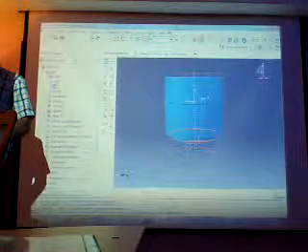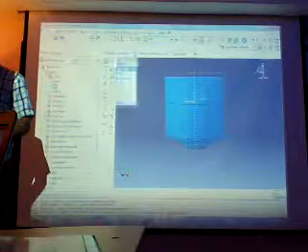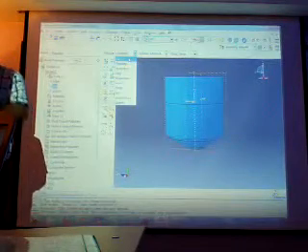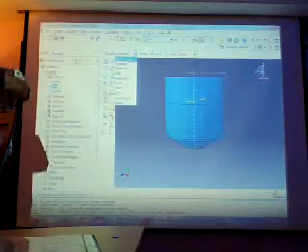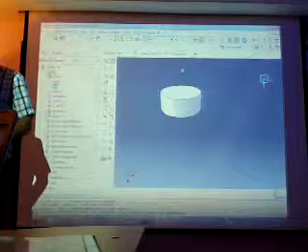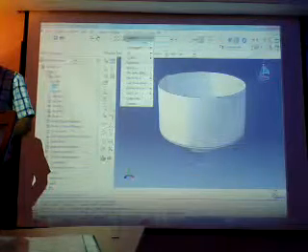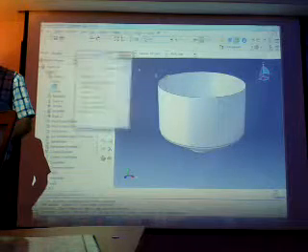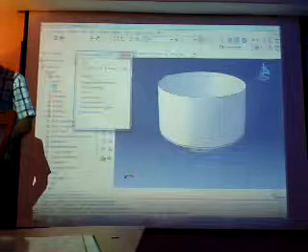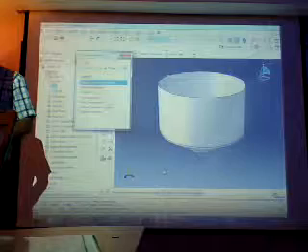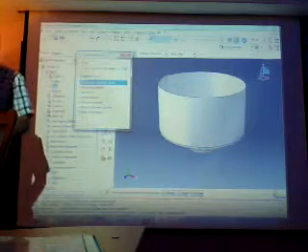For simplicity in assembly, we also need to define a datum plane for the die to control the position of the billet. I go back to the part, the die, and for this one also I'm going to take a datum plane and principal plane. Now we need x set.